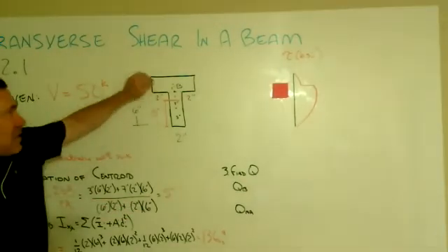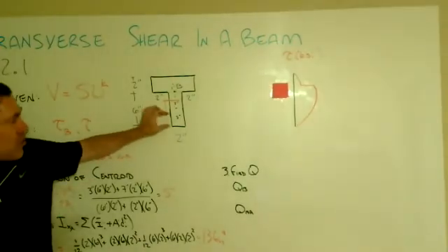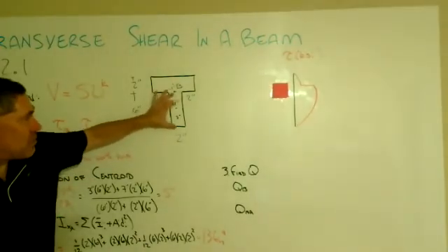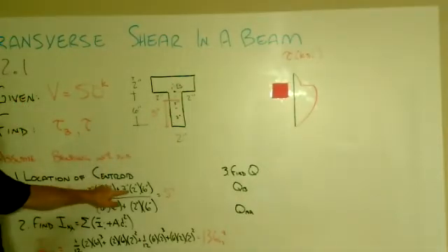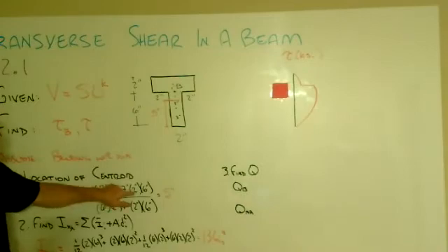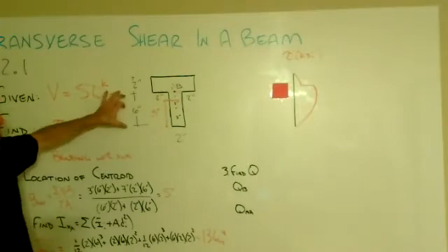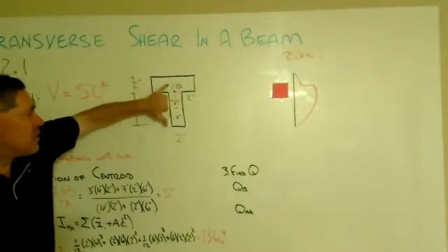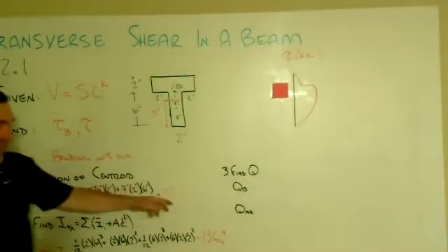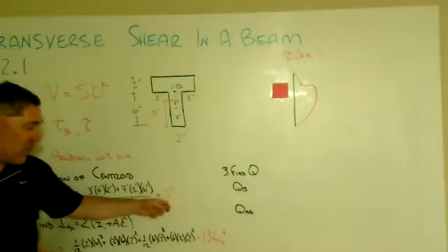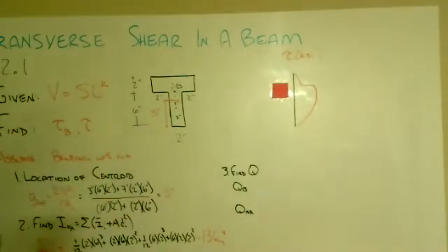So I do the bottom piece here and then the top piece. The 3 inches is the centroidal distance to this rectangular piece from the bottom. So that's 3 times the 6 times the 2, plus the moment arm for the second piece times its area. The second piece is this 2 by 6. That's up here at 6 inches plus the 1 to get to its centroid, again measured from the bottom, and you come up with the centroid of the whole composite at 5 inches, and that's the location of the neutral axis.